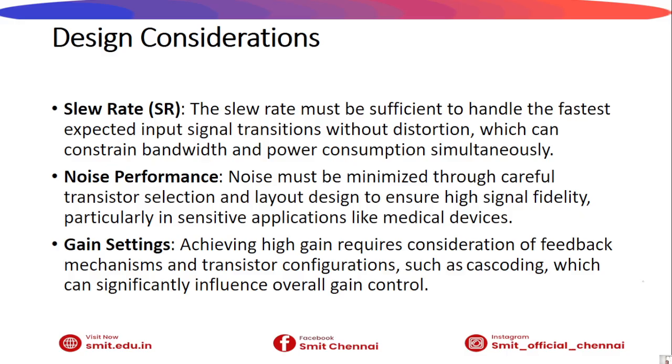Noise performance is another critical aspect. Minimizing noise means careful transistor selection, considering their intrinsic noise characteristics, and meticulous layout design. This is especially true in sensitive applications like medical devices, where even tiny amounts of noise can obscure vital signals.